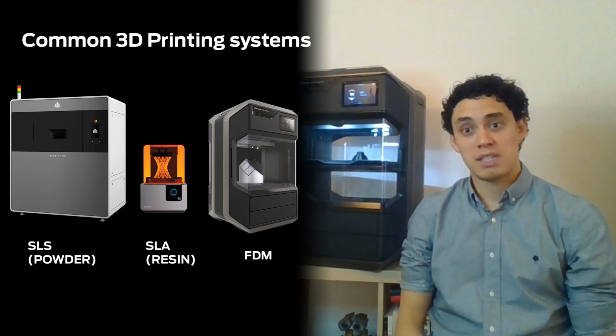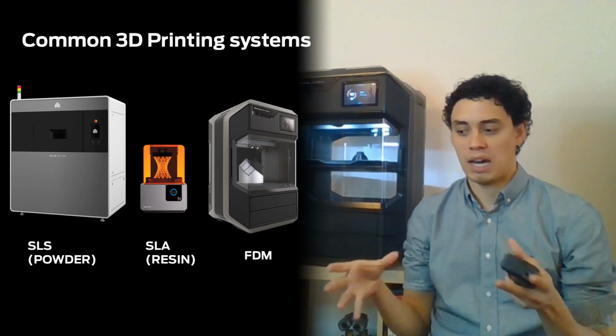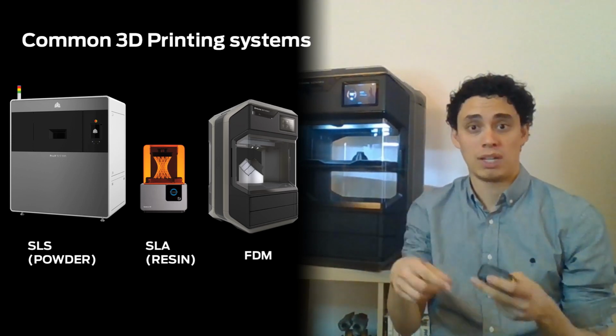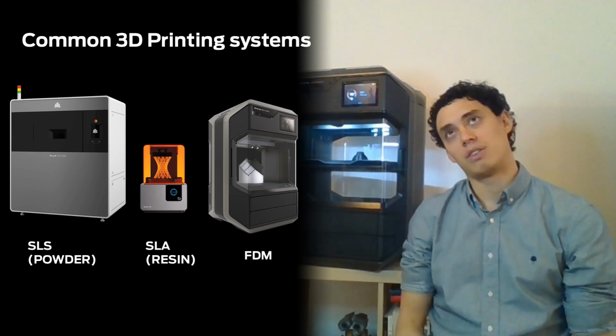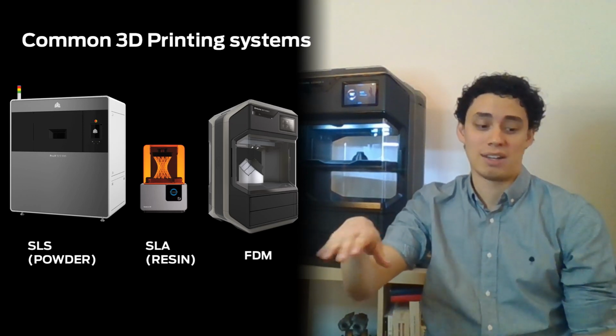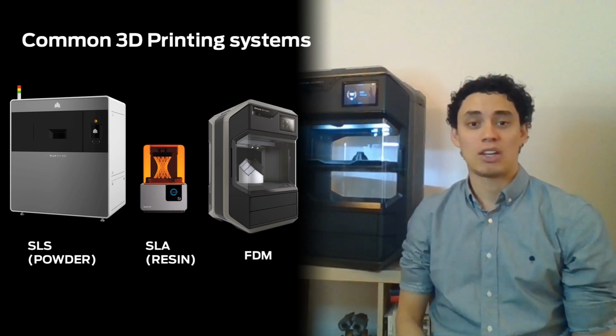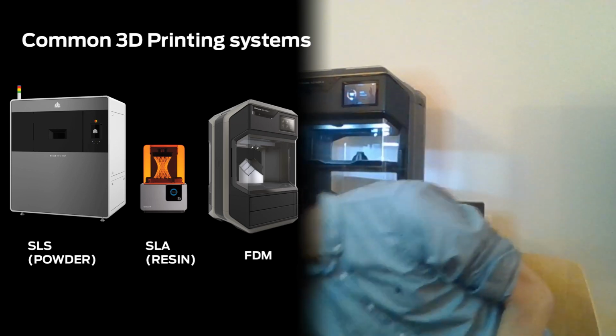It draws specifically in the resin-based printers. It will draw against a resin and slowly cure it, right? So that allows you to have very intricate parts, but it's hard, if not, I would say, impossible to print with multiple materials because you can only have one type of resin. And what that means is that you cannot have soluble supports, you cannot have anything other than breakaway supports. And I'll talk about that in a second.